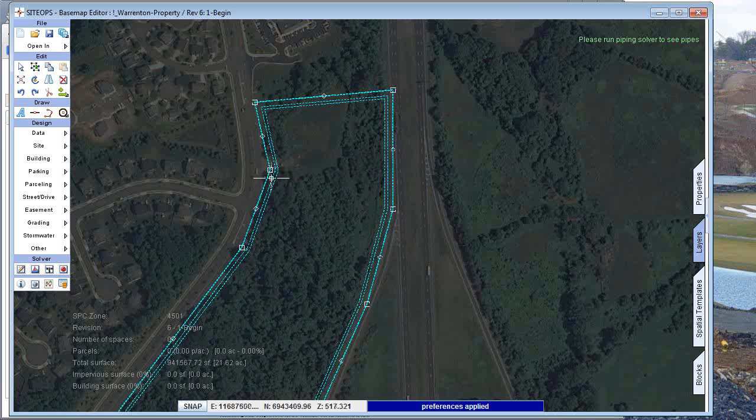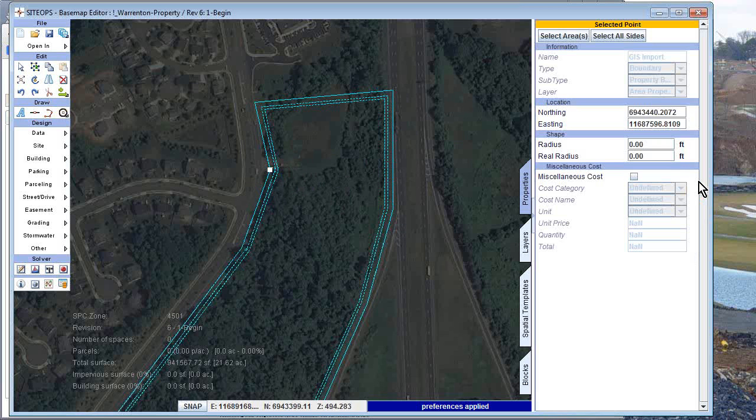All right, so that's where we started. Everything in here is not only linear as it appears right now, but it's also curvilinear. And so if I go ahead and grab that PI and then look at my properties, I can change the radius on that PI, let's say to 500. And so now I'm closely matching the road here.